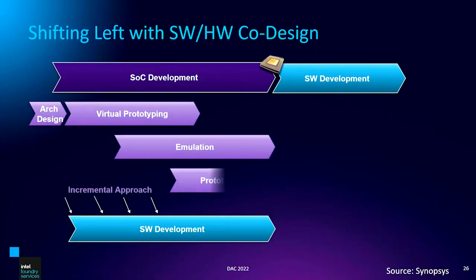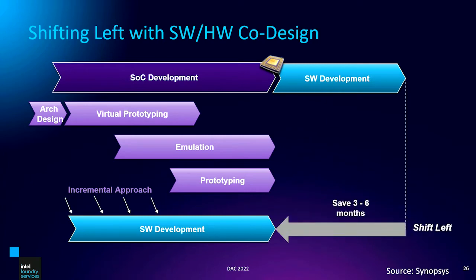Next, and this is courtesy of Synopsys. Thank you for Synopsys for providing this. There's the concept of shifting left with software and hardware co-design. So the concept of shifting left software is not new. The concept of doing virtual platforms, prototypes, FPGAs, things like this is not a new concept. However, what is new is when we start developing chiplets, we've gone from a monolithic device to a segmented device. So you could argue that what we need to do is just have the software be aware of these different devices, right? You could argue.